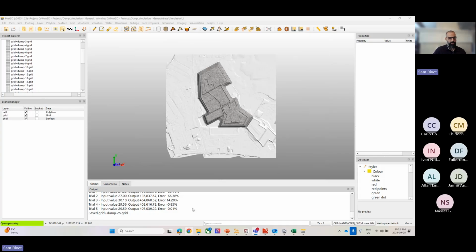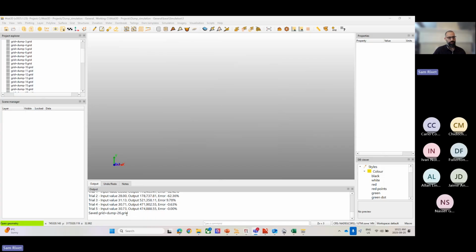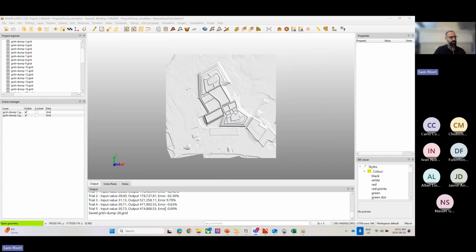And you can see here in the output window, it's goal seeking the appropriate elevation until it reaches that error tolerance it's comfortable with. And now it's just creating that first period grid with all that volume allocated to it and merged into the different cells. Once that's complete, it's going to create the visual, the period map, and then output this, update the spreadsheet.